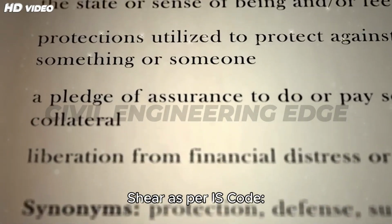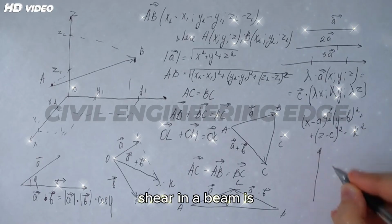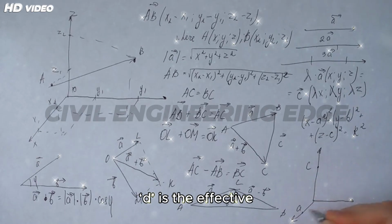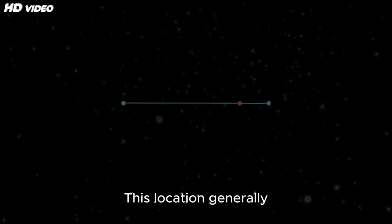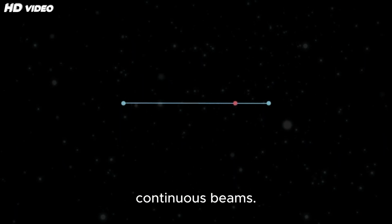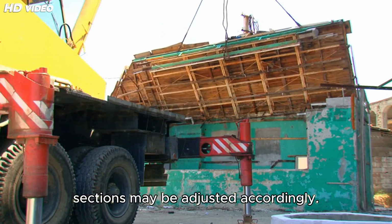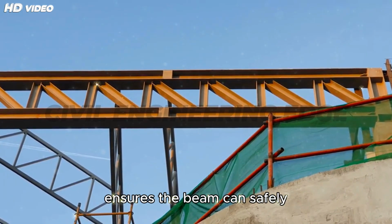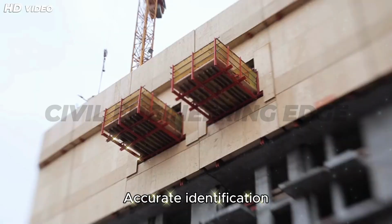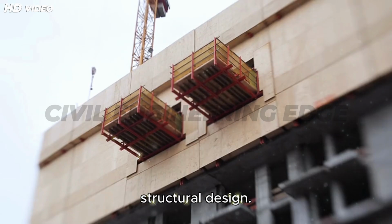Critical section for shear as per IS code. As per IS 456:2000, Clause 22.6, the critical section for shear in a beam is taken at a distance d from the face of the support, where d is the effective depth. This location generally experiences the maximum shear force in simply supported and continuous beams. For beams with concentrated loads near supports, critical sections may be adjusted accordingly. Designing at this section ensures the beam can safely transfer loads to supports without diagonal cracking or sudden failure. Accurate identification of the shear critical section is essential for safe and economical structural design.